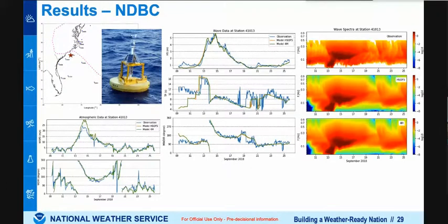One with 200 meter coastal resolution, and the other with 120 meter resolution with 4 million nodes. Obviously there is no significant difference at this location because the mesh resolution here was almost close to each other. But when we move to the landfall, nearshore and overland, the differences show.